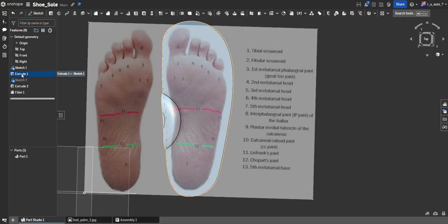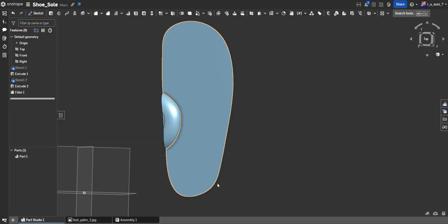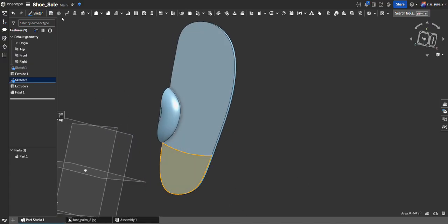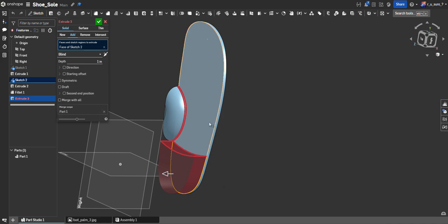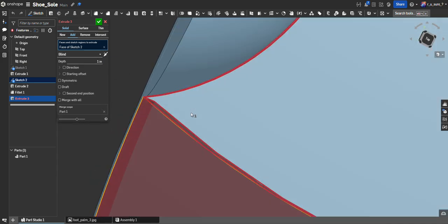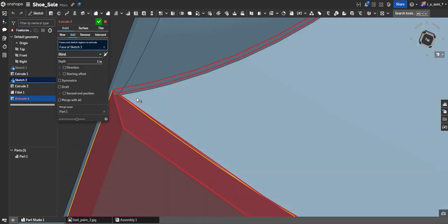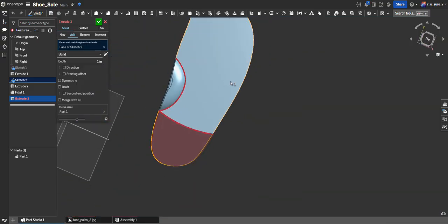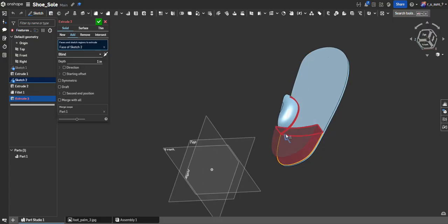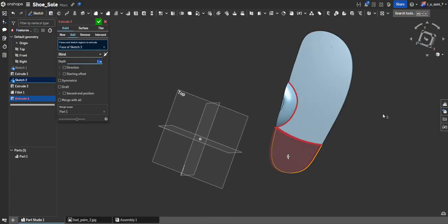And now hide it there. You see that? Now I have this heel area here. I'm going to extrude it up by 1 inch. And it says that there are some changes there that need to be made. I don't believe it's with here. It seems to be with the intersection.